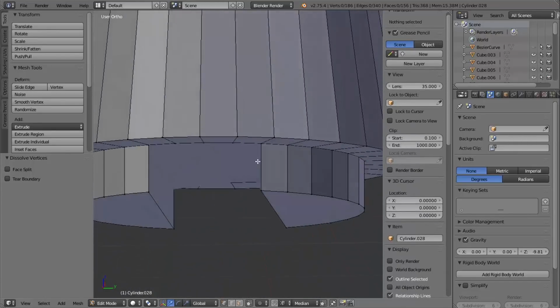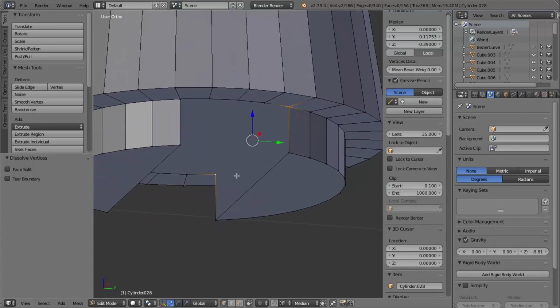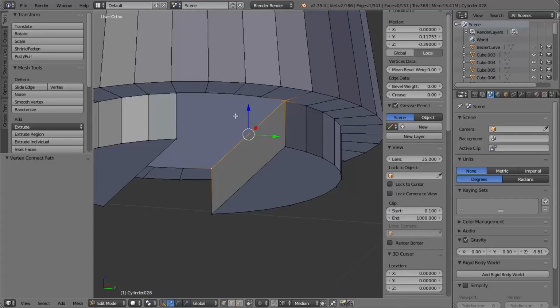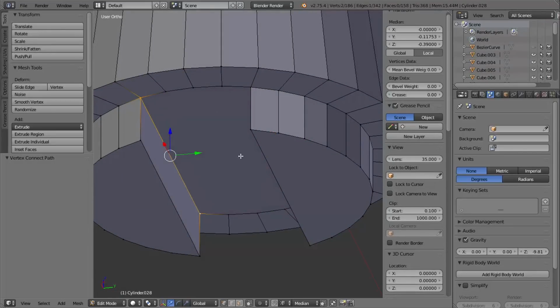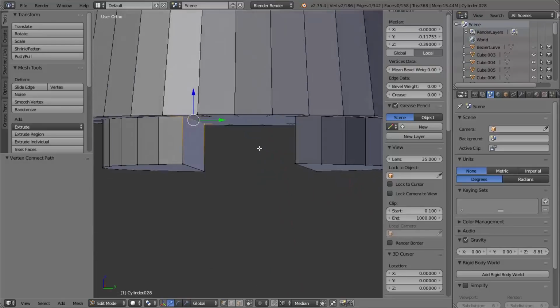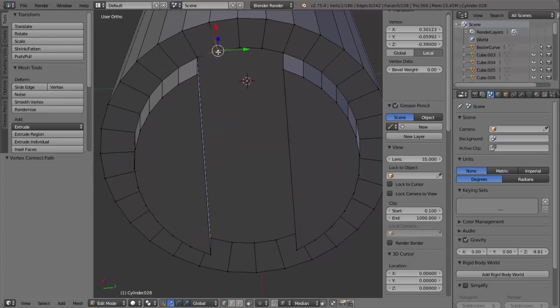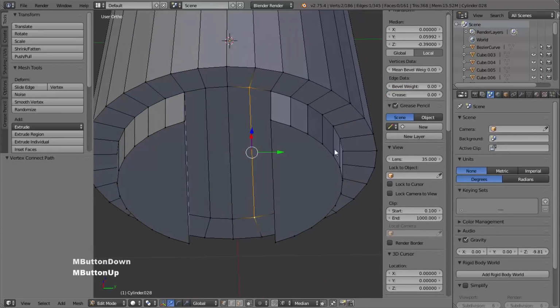And now I want to select the vertex that's at the bottom of this shape here, and this will make up the side of the notch that I'm creating. So with those two vertices selected, I can press J, and that makes much more recognizable geometry there. So going back to the other side and doing the same thing. And so now I've made this kind of clearance in the center. So while I'm here, I've got an n-gon, so I'm going to clean that up. I'm just going to select the opposite vertices and connect them with edges with J. And yeah, I think that's okay.